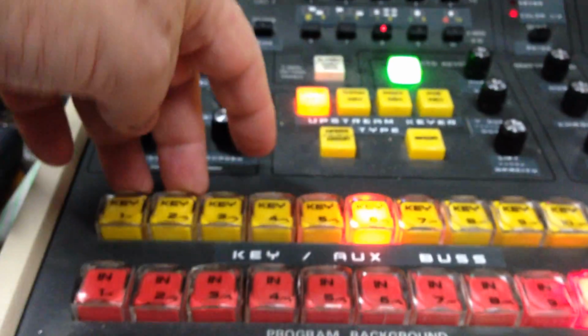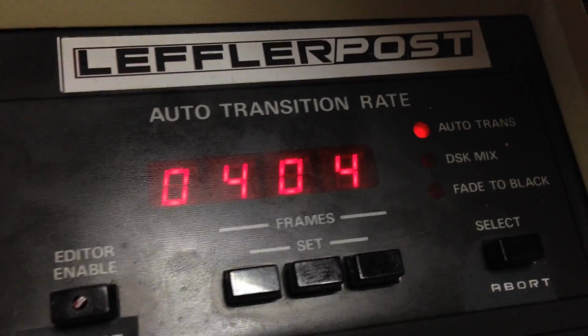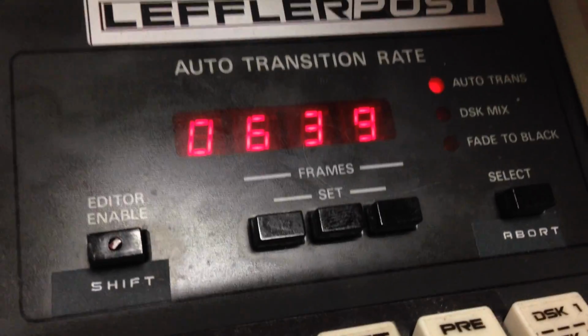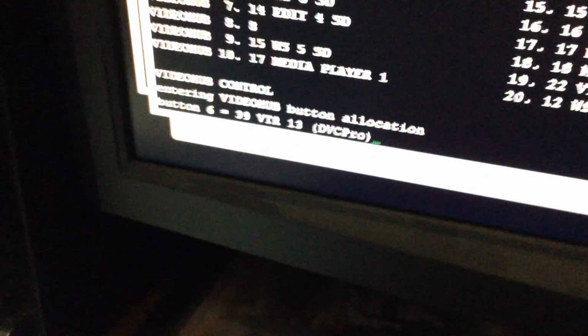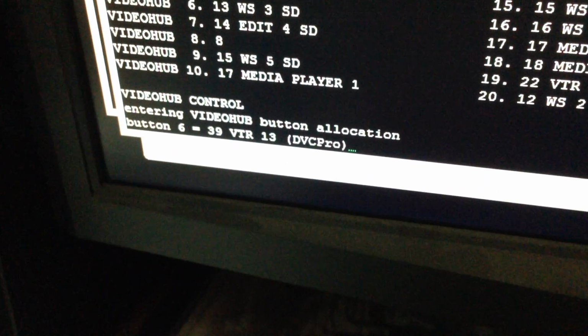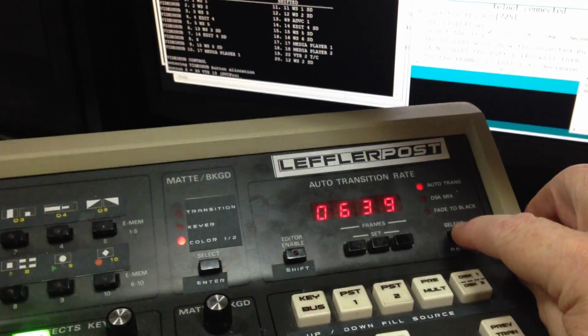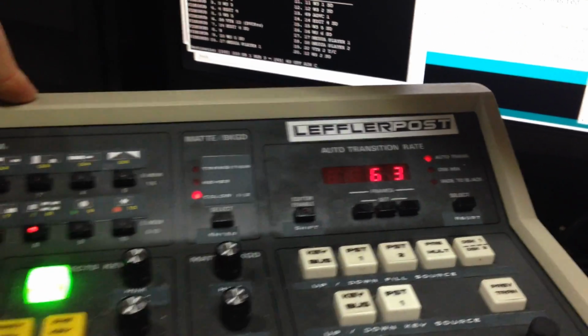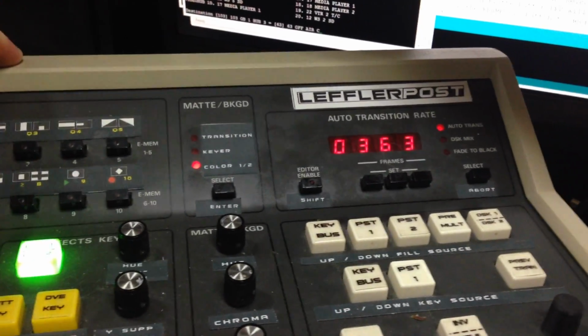Anyhow, that's just incidental. So then as I switch away, let's say to button 4, you can see button 4 here has got input 4 selected. But if I go back to button 6 again, you'll see it's got that source that we just selected, so they're permanently stored. So that's a very quick way of doing it using the panel buttons. If I now hit exit or abort, I'm over here, let's change hands. So we just hit focus, change hands, and now I've come out of button programming. It's gone into normal Videohub control now, but we'll come out of that as well.